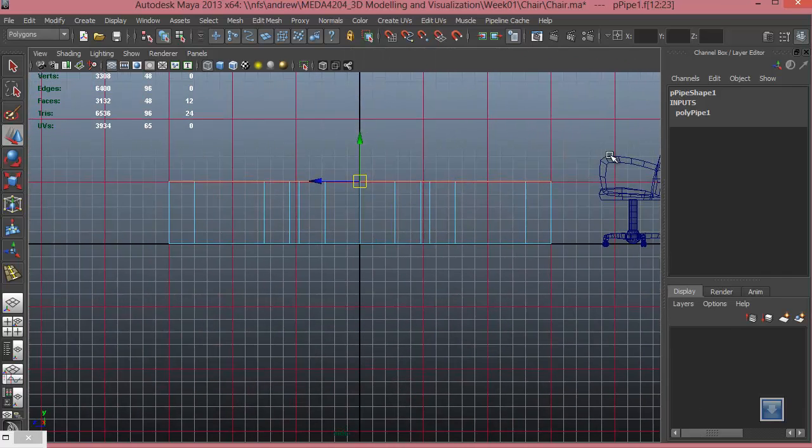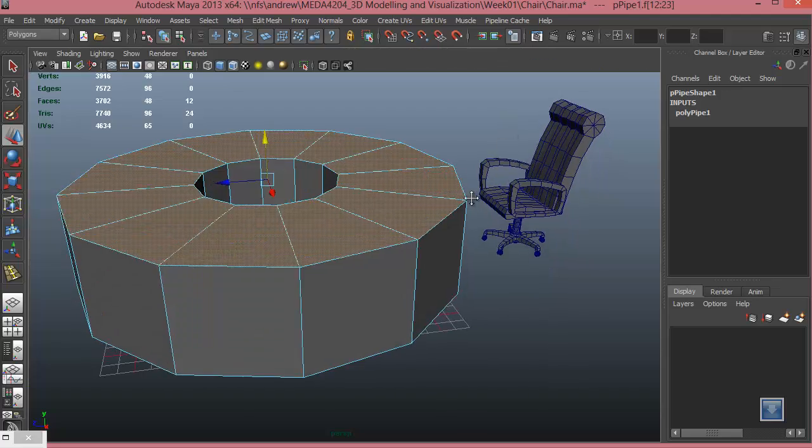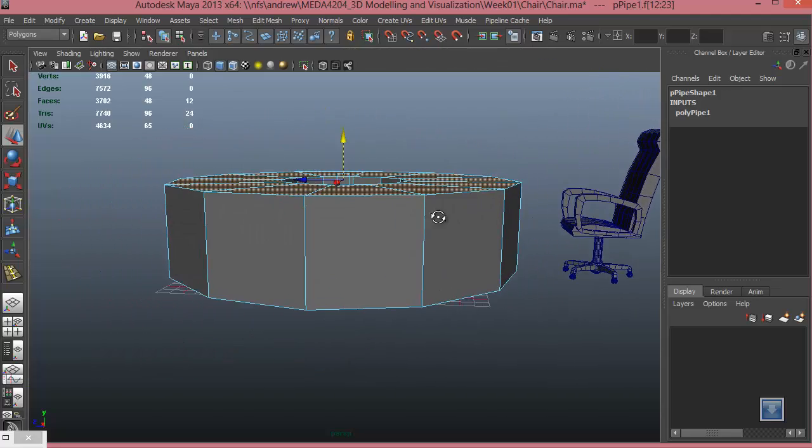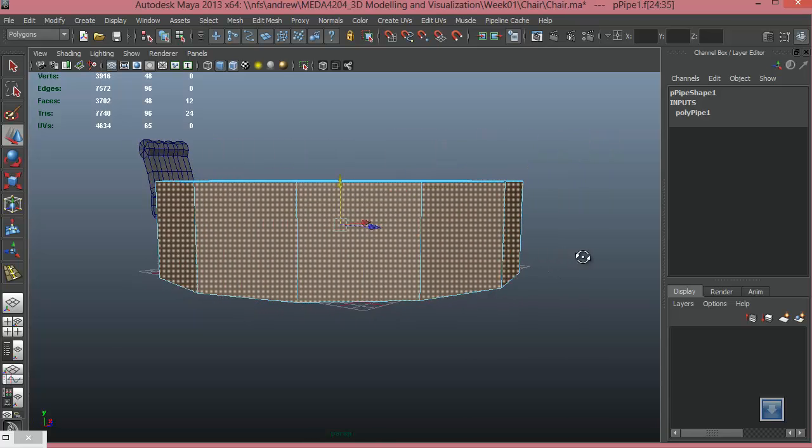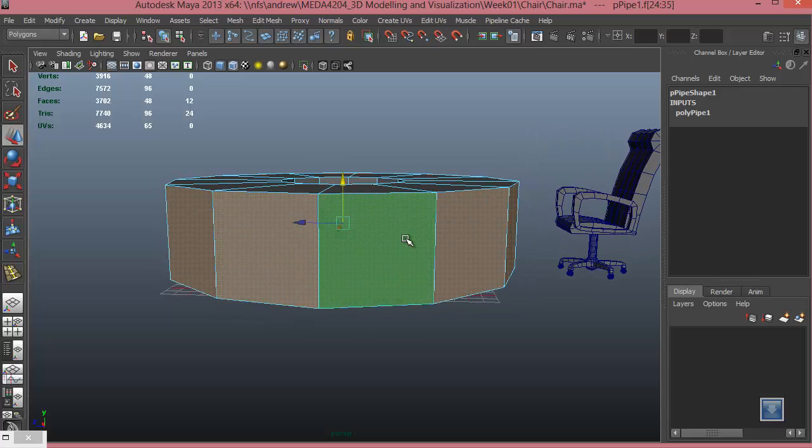Go to the side view. I can see I want to bring this up to this handle, so I'll push it up somewhere there. Okay, that's good. Now let's go ahead and create some extrudes. Select one, hold shift key and double click on the second one. That selects all these faces.